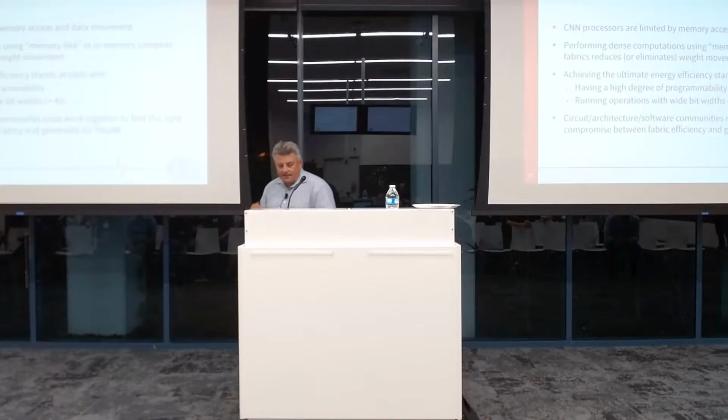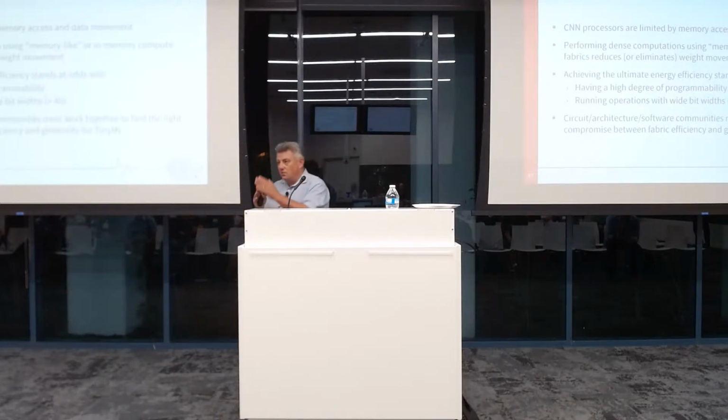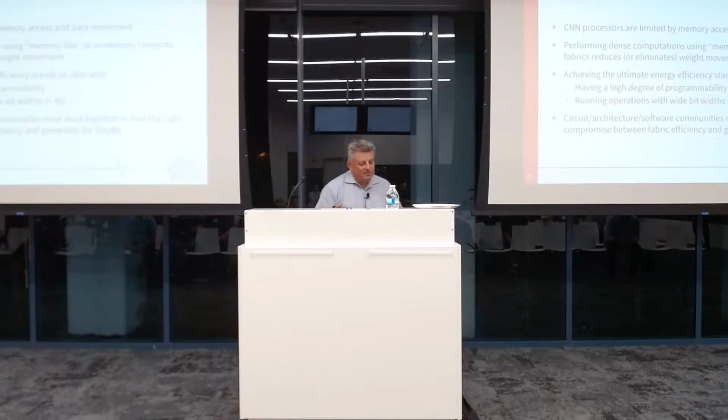Now, that paradigm still stands at odds a little bit with what the software guys want, because a very high degree of programmability would mean that I would somehow have to be able to change the number of tiles on the fly or something like this, or maybe change the number of bits, do 4 bits here and 16 bits there or something like this. This is going to be very, very difficult. And so my perspective is the following. It's not going to happen that you get the most efficient fabric that is highly programmable at the lowest cost with really high bit widths and so on. You're not going to get all of the above.